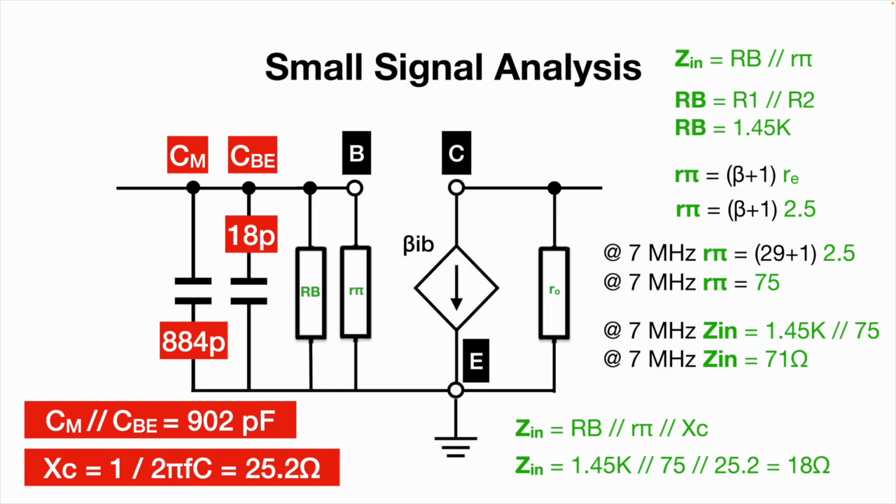So there's all kinds of reasons why these figures can be different. Bear in mind that my calculations are assuming certain things. They're assuming that the capacitance between the collector and the base is indeed 4 picofarads, as the datasheet suggests, but the datasheet is produced by a company that certainly didn't produce the transistors that I purchased, so who knows? My individual collector base capacitance on that particular transistor may be more, maybe less, so that will affect things.